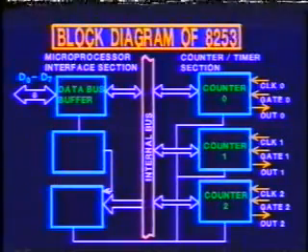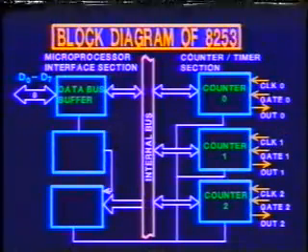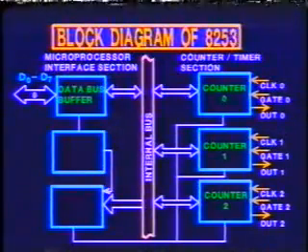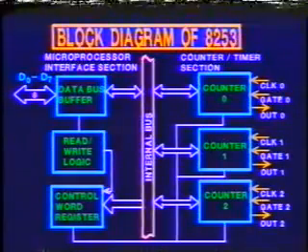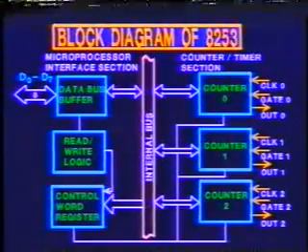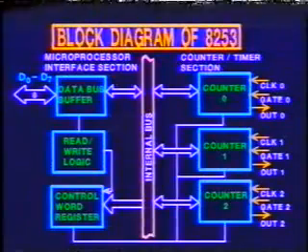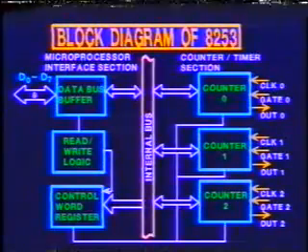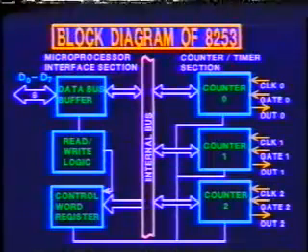The 8 data lines D0 to D7 are connected to the data bus of the microcomputer. Each counter presents a logical register to the CPU. The device presents a total of 4 logical registers to the CPU, one for each counter and one more for the control.